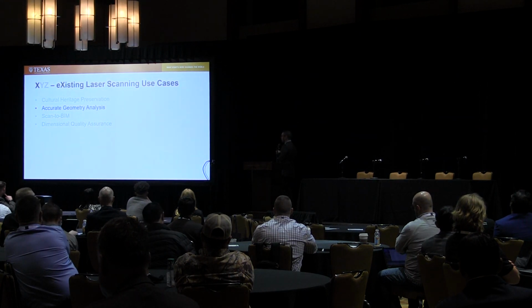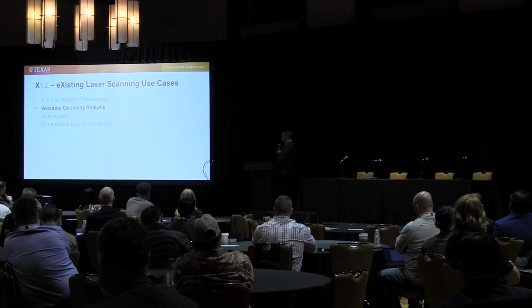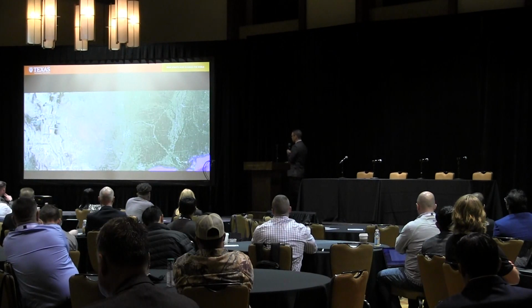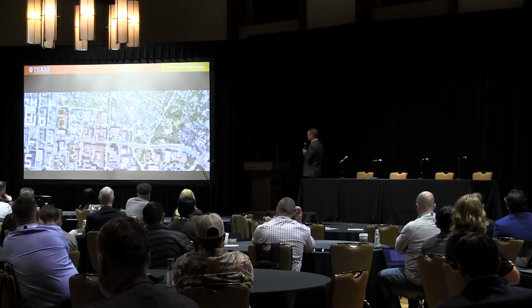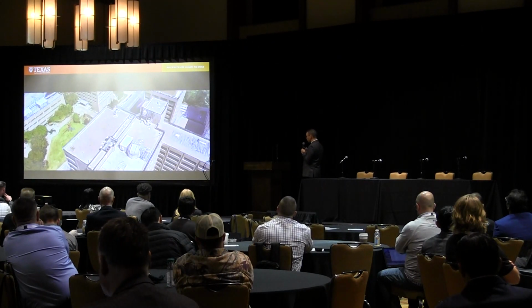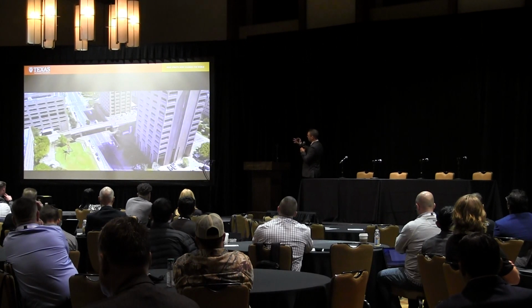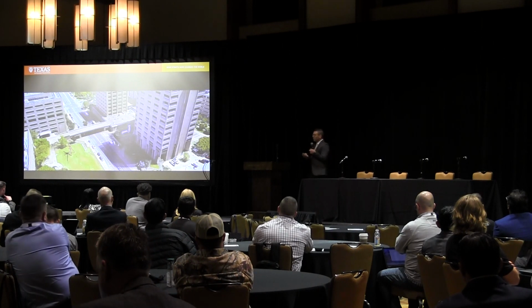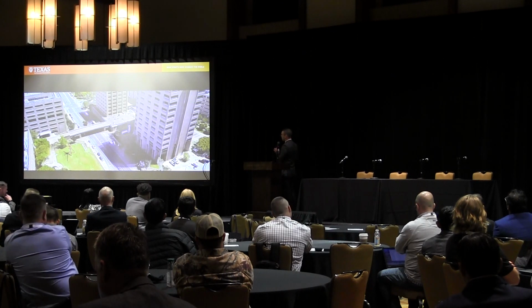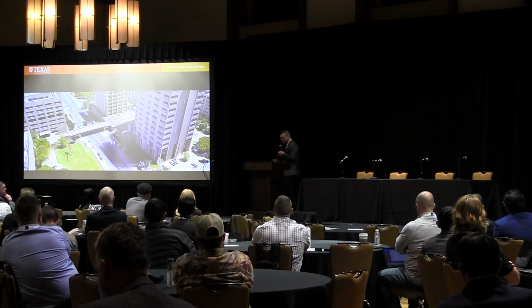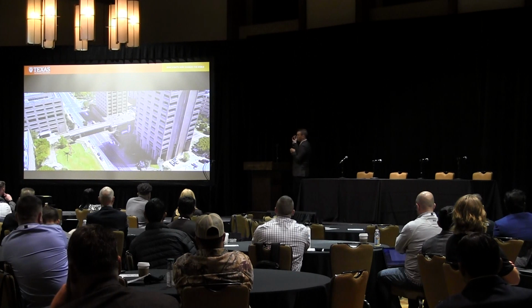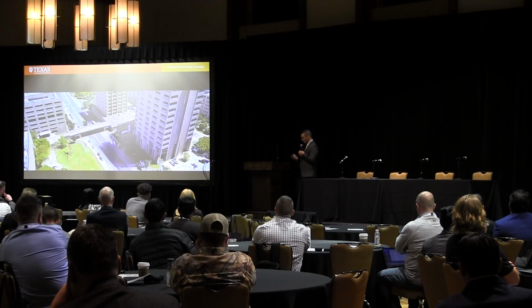The second application that I want to highlight that laser scanning is great for is conducting very accurate and detailed geometric analysis. If we look at a sample project just up the road here, we see the emergence of aerial imaging, so here is a GPS-based capture of an engineering corridor. It can be used to inform a good variety of geometry. But if we want to use the data from this type of capture for detailed engineering assessments, we really run into challenges, both in terms of the fact that this could be from a year ago, and it really is not resolved to a level of detail that we need.